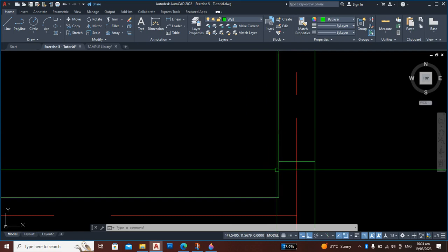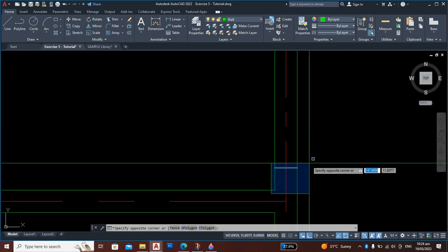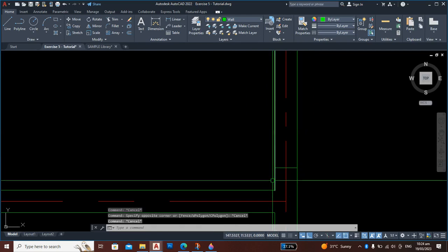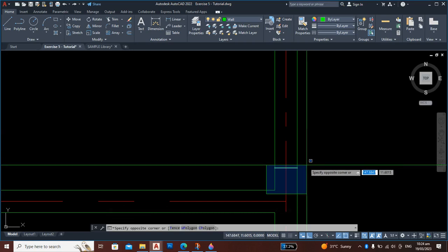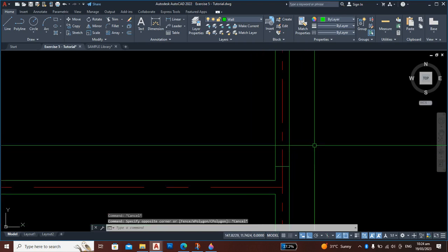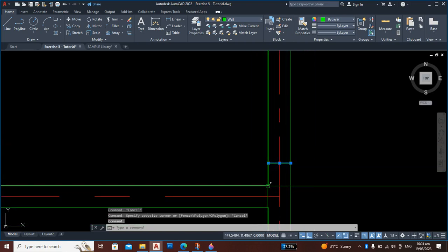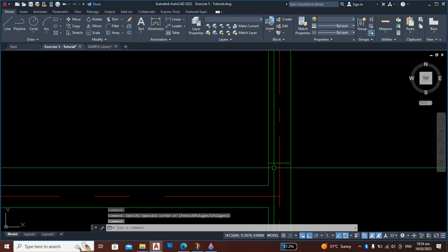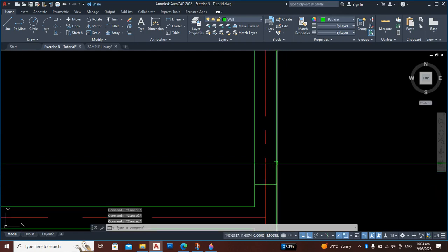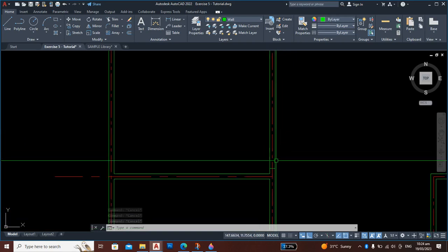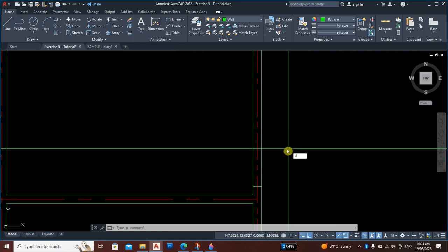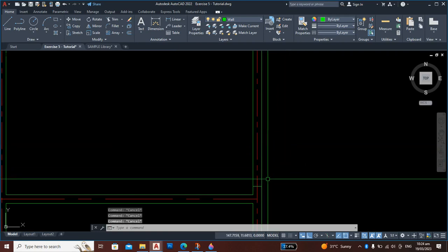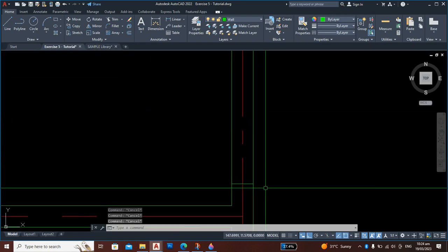So to avoid that, we have to extend, or there will be a part of a wall, partial wall here. So ideal is 0.10. You can make it larger depending on the availability of the space. But let's say 0.10 only from here. Then of course the width of your door here in the bedrooms is 0.8. So type 0.8, but of course you have to make first the command.